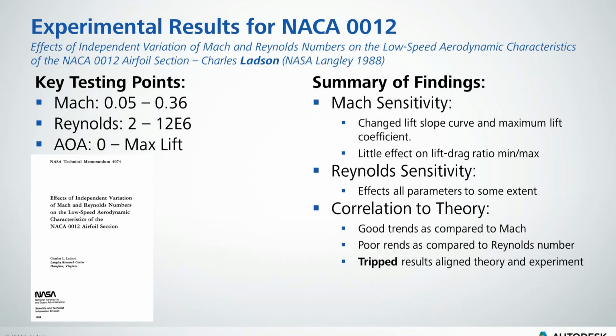And that basically creates an extra layer of turbulence to that leading edge. Otherwise, with this airfoil, you get purely laminar flow on the leading edge, and this way you're going to get turbulence throughout the entire airfoil. Okay. And even within their test data, they actually did not really get good comparisons to their theory back then, unless they were actually comparing to those tripped results. So I found that pretty interesting myself.